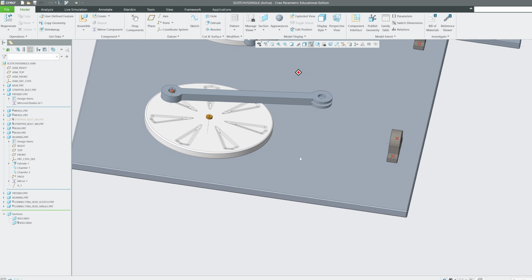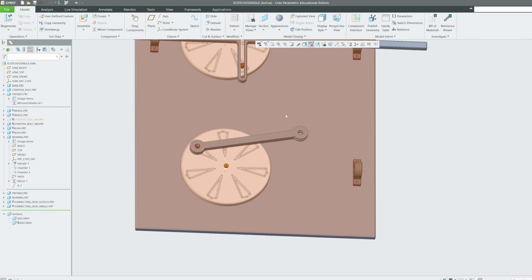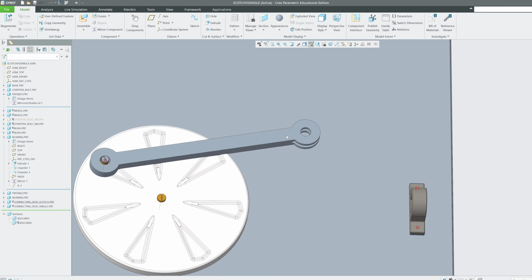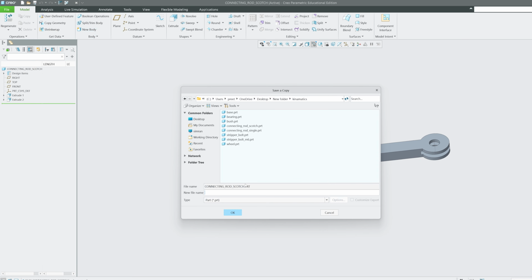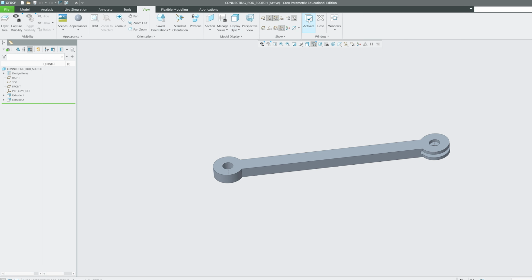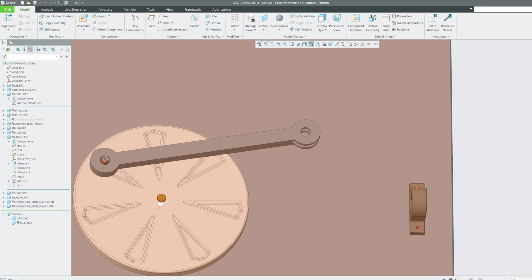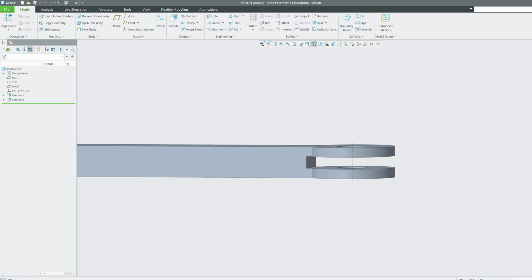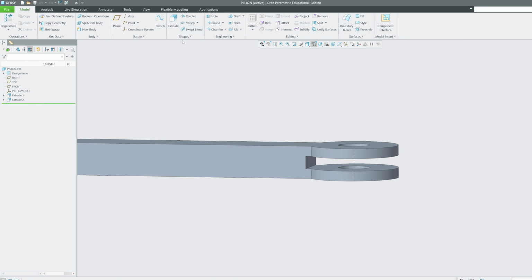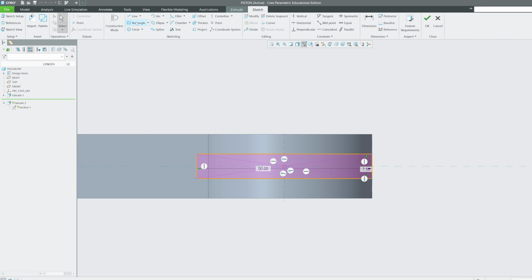Okay, so the last part of this puzzle is this portion which would act as a piston. So let me create this. Probably I'm gonna copy this. This time I need to be careful. Save as, and I'm gonna literally call it piston, and I will take care this time. Like, I'm not going to edit this one. Instead, I'm gonna edit piston. So I need to make a male part here now. So let me actually go back here in extrude, and I can simply create two rectangles.